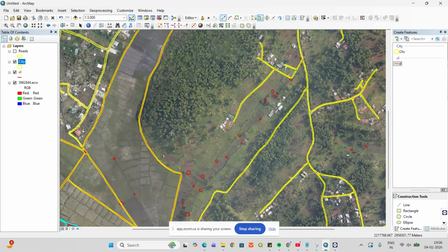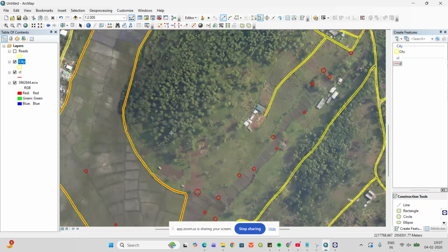So that is why I told you it will take us 2 to 3 months. We'll roam around every part of the state to know what is the maximum height of trees and where it is present. And based on all those parameters only, we'll be fixing the flight planning. So we'll create a KML, but our flight planning height parameters and all will be done only after field checking, because we have to check for wind speed, everything, at different locations.